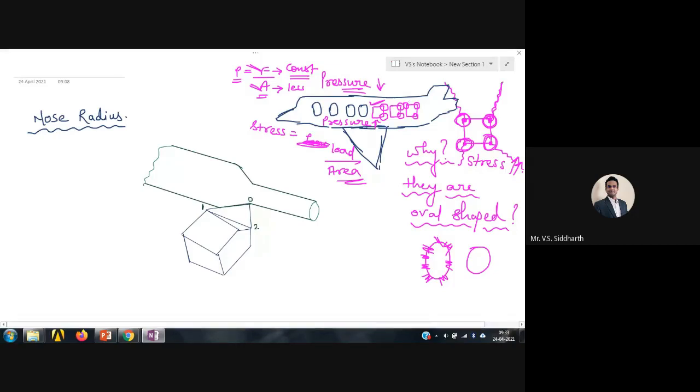Midway, aircraft have blasted, because a small crack propagated until it became so dangerous that it gave rise to a big blast in the body of the aircraft. Why? Because air is at a higher pressure inside and a lower pressure outside, so the aeroplane acts like a balloon.